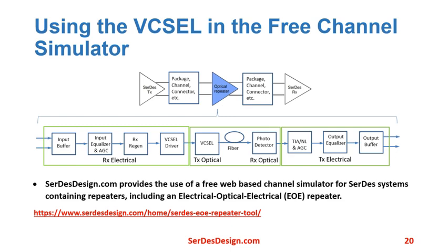This is the typical block diagram shown earlier for an EOE retimer in a SerDes system that is fully configurable in the free web-based SerDesDesign.com channel simulator. This free web-based tool includes IBIS-AMI model generation for the receive and transmit sides of the repeater.